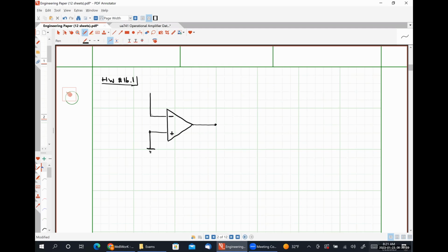We have some feedback resistance connected between our inverting input terminal and our output terminal. So let's make this easy and call this a 5 kilo ohm resistor. Here is the output voltage that we are trying to measure. And if I'm not mistaken, over here on the left, we have a current source. And let's make this a 1.5 milliamp current source having this particular direction.